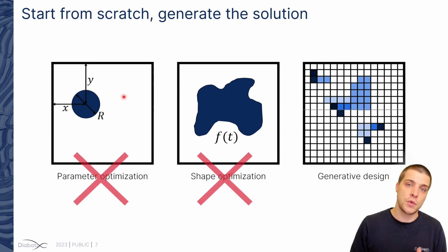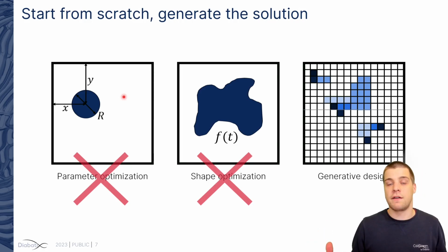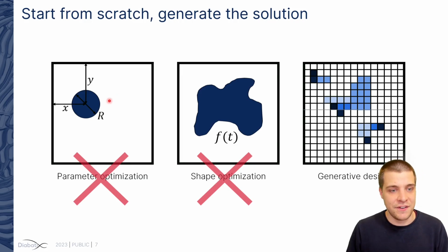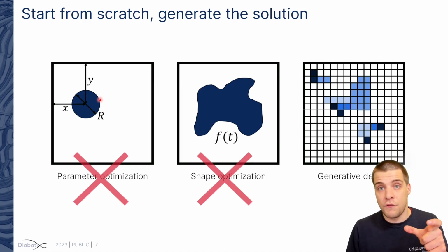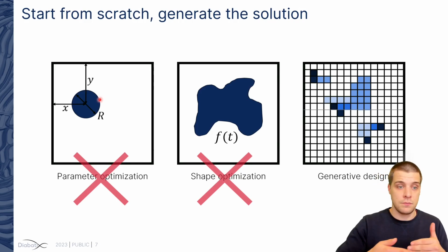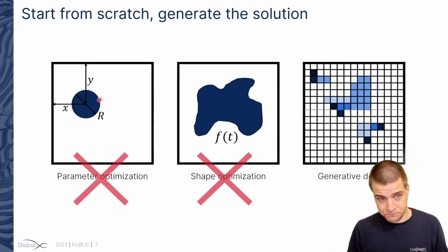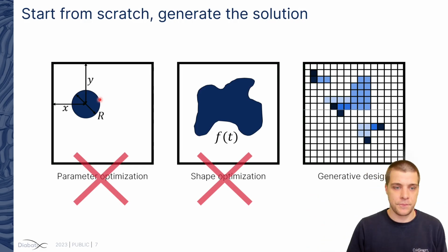And for each of those cooling solutions, you find a set of parameters that basically describes your entire heatsink. I've chosen here the example of a pin. For a pin, you can describe the diameter of your pin, the height of the pin, the spacing between the pins, both in X and Y. And that limited amount of parameters basically describes your entire pin heatsink.